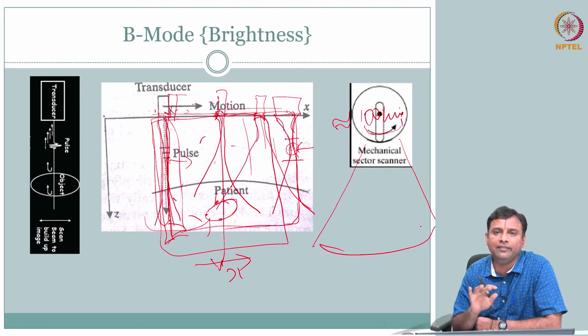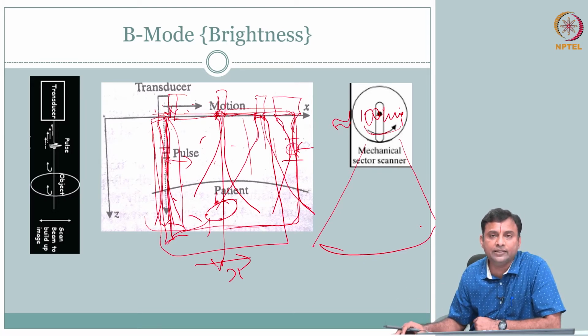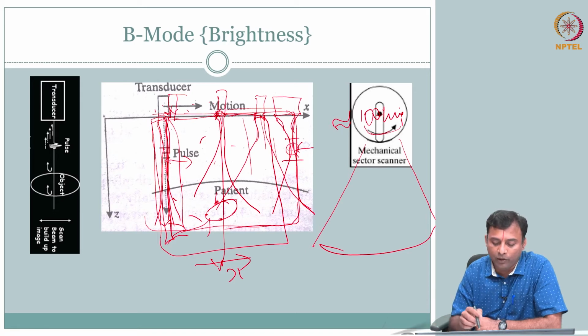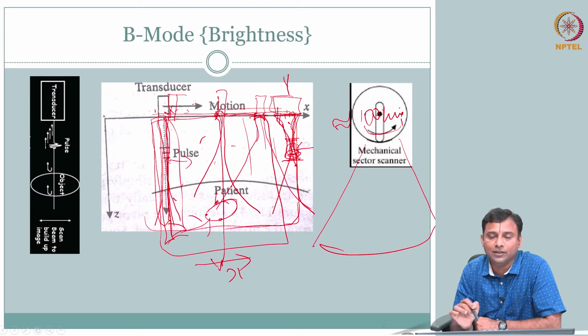The reason I just want to leave it here is that this has a lot of challenges, as you can see. I can have only one focal location because the lens is going to be manufactured with one particular curvature, so I can have only one focal depth. If I have a big transducer, I can have a narrow beam, right? But then I am still averaging over all the area to get one thing. And the wider and narrower I make it, the shorter my depth of focus will be, so my resolution will be spoiled.